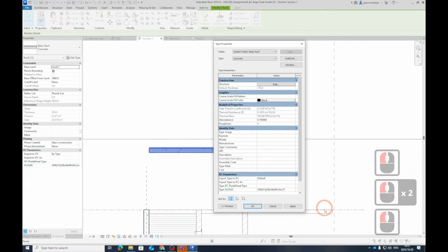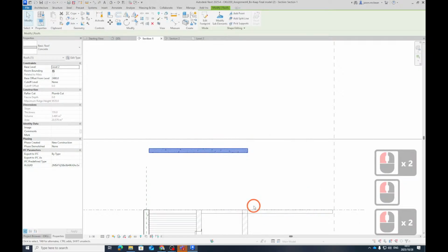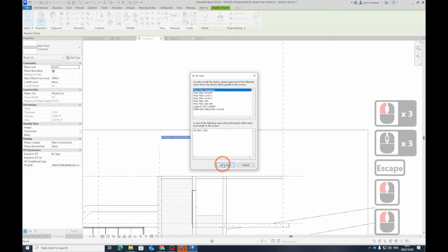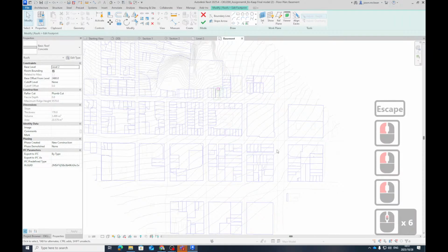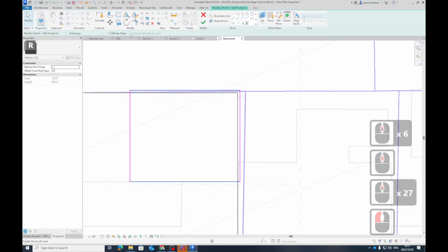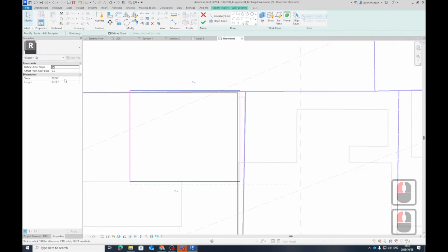But you could have done all of what I've done now using a floor slab. Yes. You could have used a floor slab as well. But it's good to know. Maybe one last little trick. One last trick for the day. If you want to get these things to have slopes, you just say define slope. This is very cool. Those are gables. Define slope 10 degrees. Let's make it 30 degrees, just like this. This is how easy it is to do a roof actually. If you kind of know what you're doing.